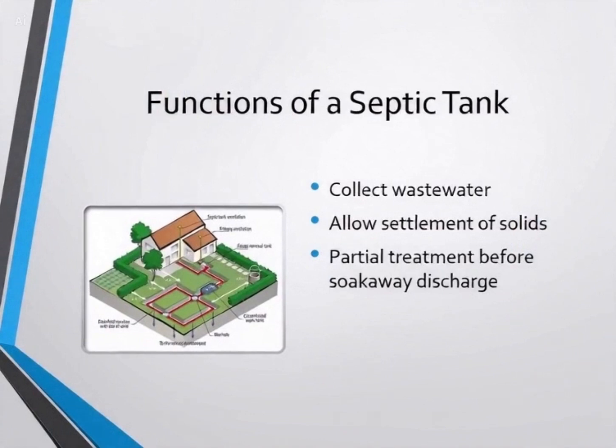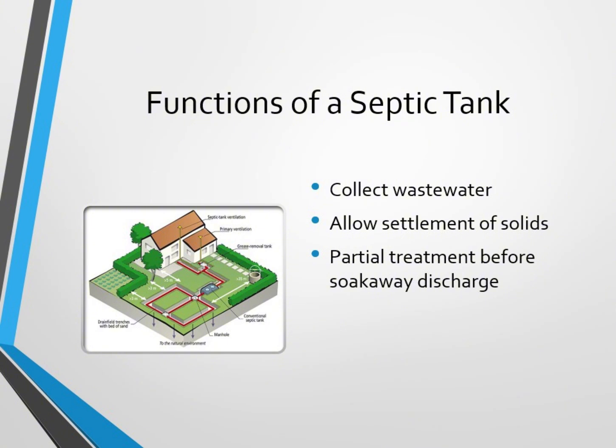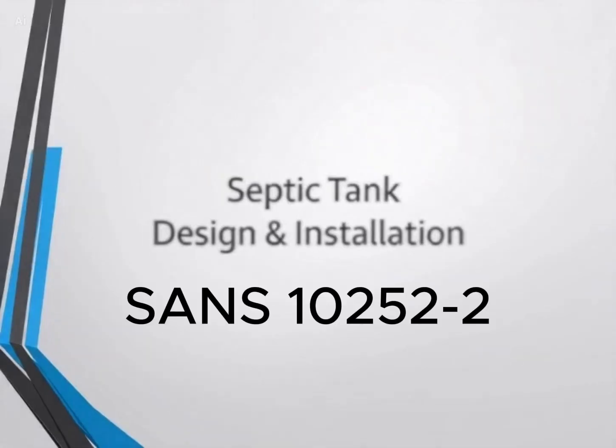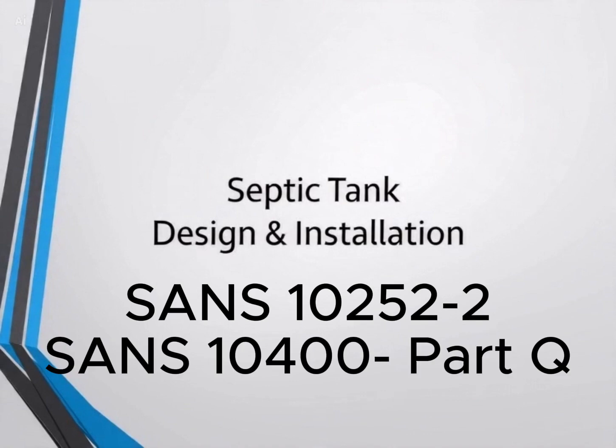Inside the tank, heavy solids settle to the bottom as sludge. Oils and grease float to the top as scum. Liquid effluent flows out into the soakaway. The septic tank must therefore be watertight, be structurally stable, and provide enough retention time for settlement. We refer to SANS 10252-2 and SANS 10400 Part Q as the primary design standards used in the following example.